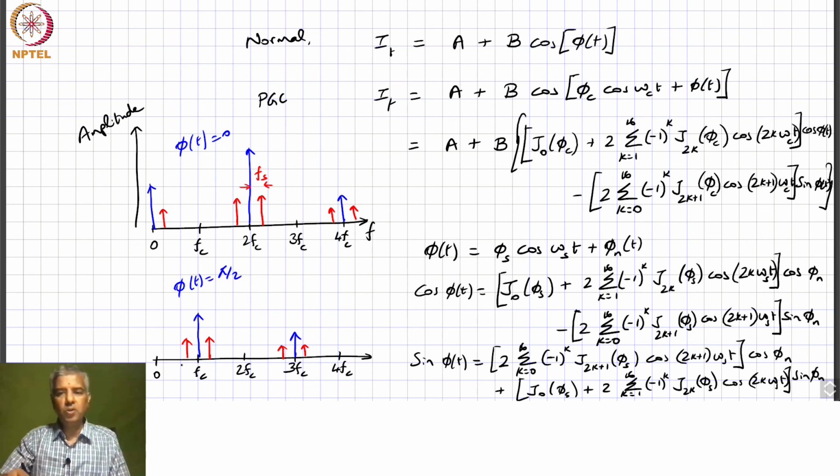The main peaks, mind you, are what you have chosen. So, you have chosen say 10 kilohertz. Then this corresponds to 10 kilohertz, this is 20, this is 30, this is 40 kilohertz. So, you know where those frequencies are. You basically lock into those frequencies and then look for components around them, and those components are going to tell you what is the actual acoustic signal that is incident on the hydrophone.